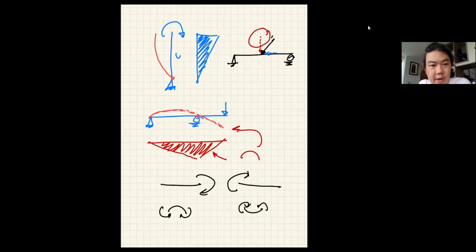So if you have the load that is not, say, perfectly perpendicular to your member or the principal axis of your member, it is your job to realize that only the component that is perpendicular to your member will produce bending moment. So if you have a case like this and then you proceed to use just this one to calculate bending moment, you are wrong because you are including the horizontal or parallel component in the calculation of bending moment as well. So that's a simple idea, really.